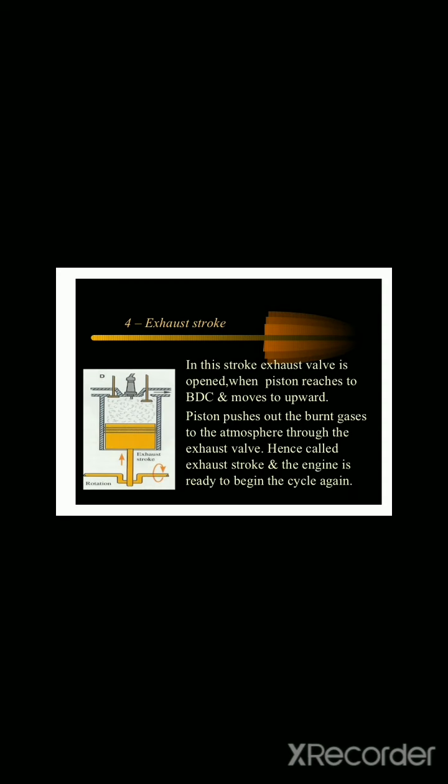Exhaust stroke. In this stroke, the exhaust valve is opened when the piston reaches BDC and moves upward. The piston pushes out the burnt gases to the atmosphere through the exhaust valve, hence it is called exhaust stroke, and the engine is ready to begin the cycle again.